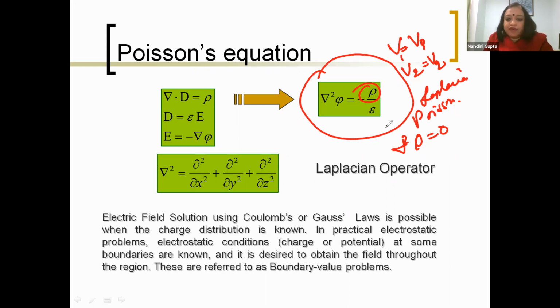We are never ever going to talk about the bound charges, Girish, because we have already accounted for the bound charges. How? By changing the value of permittivity. So whatever bound charges there are have been taken care of when we have taken an epsilon r not equal to 1. So bound charges do not enter into rho. Is this clear? See, these are things that you know, but when you actually apply the finite element method, you will have to be very clear about these distinctions, and that is why I'm spending so much time over this.